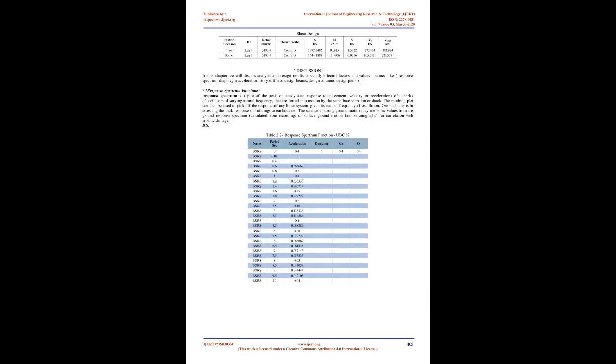The seismic forces computed by IS 1893 (2002) are found to be significantly higher. The difference varies with structure properties. It is concluded that such study needs to be carried out for individual structure to predict seismic vulnerability of RC-framed buildings that were designed using earlier code, and due to revisions the provisions may have rendered them unsafe.